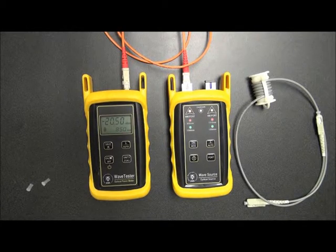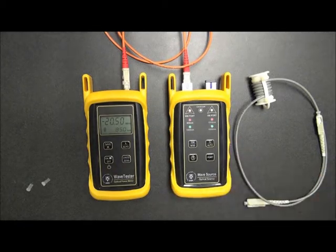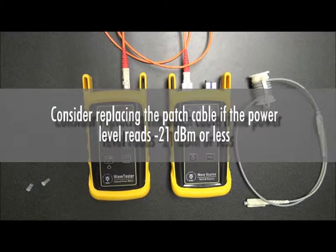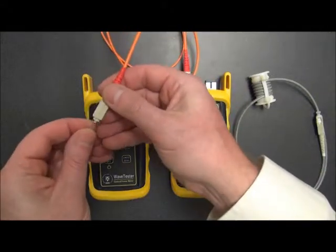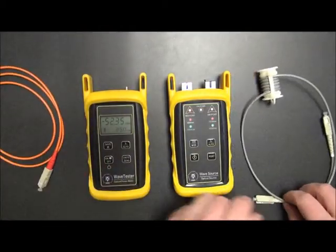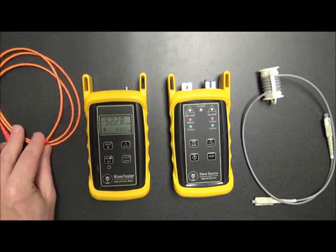Okay, now you can see you have a reading of minus 20.5. Really, what we want to see is a reading of roughly minus 20 dBm, and this is fairly close. We want to make sure that these patch cables do not exceed minus 21. That's the goal. In this case, this patch cable is okay to use. For now, we're just going to remove it from the testers, and then we're going to plug in the other patch cable. Now, we can set this patch cable aside. We won't need it for a while until we're actually taking measurements.